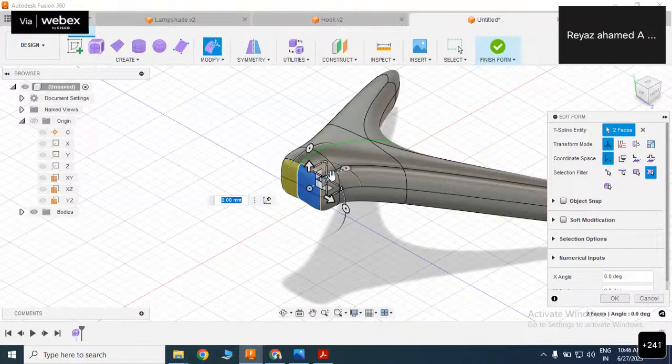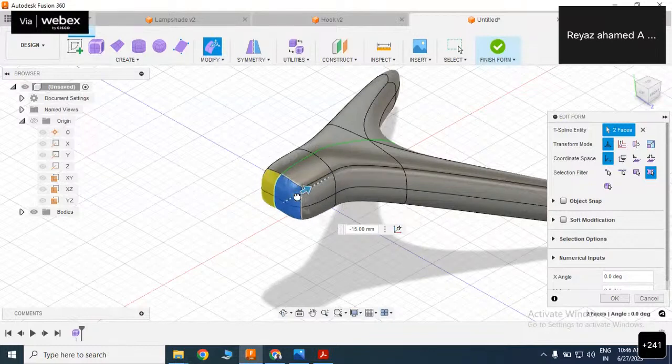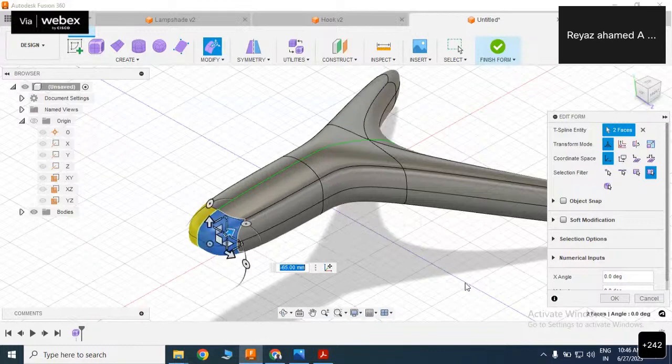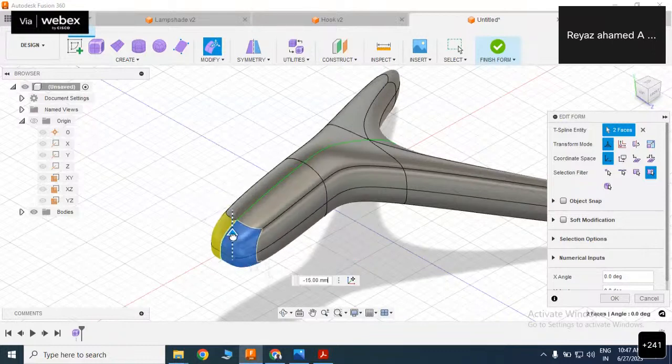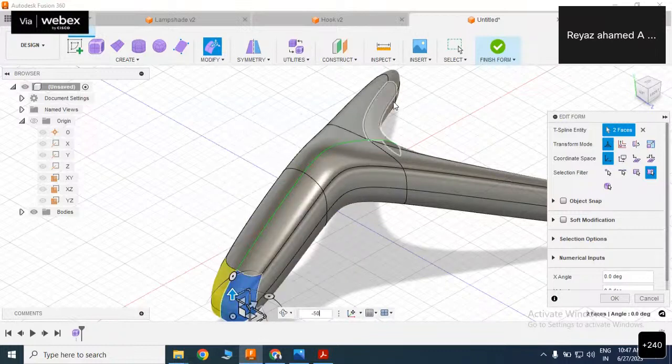So now let us move this cursor towards the left-hand direction. See, both the sides may get elongated based upon the dragger. As of now we had elongated until -65, but this much distance is not needed. So let me give the value -50. And then let us do this portion, that is also -50, because on the other side we had applied 50 mm for downward.